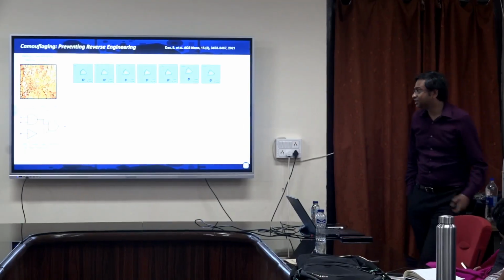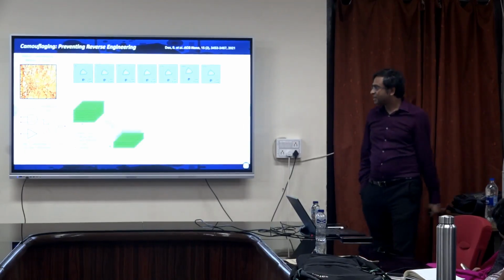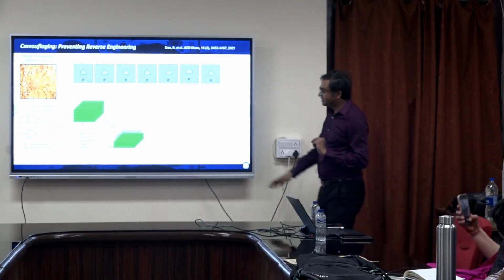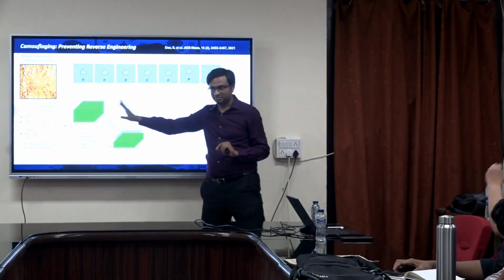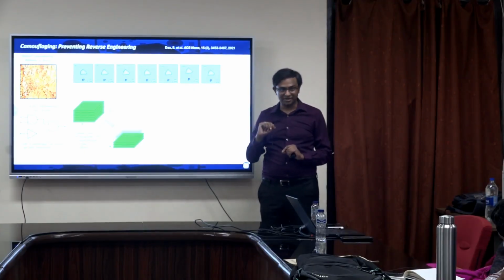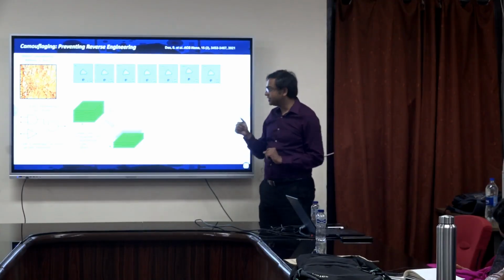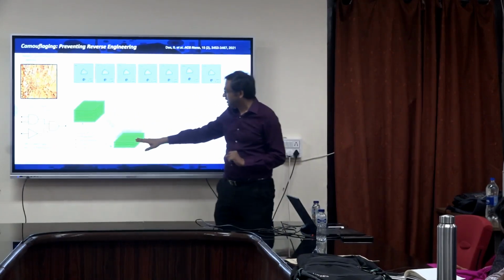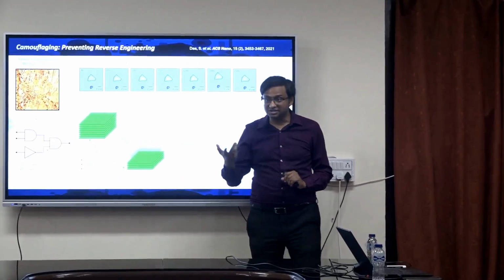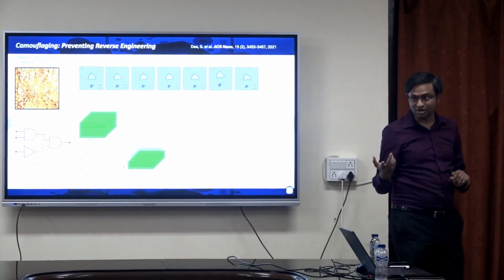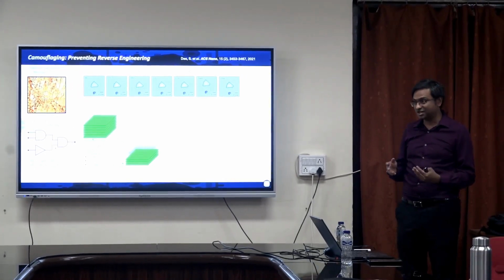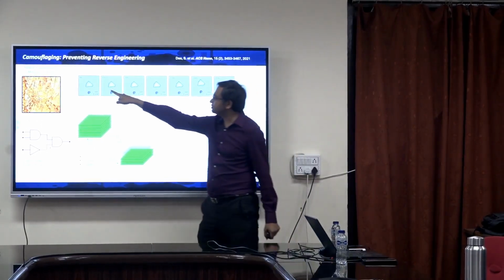That is possible with the 2D material because of this. If you have not a monolayer flake but a multi-layer flake, then this material is primarily N-type. Most of the 2D materials are N-type. Then we spoke about this oxygen plasma treatment, didn't we? When you treat it with oxygen plasma, it's a self-limiting process, but you can convert the top layer into a transition metal oxide, like molybdenum oxide or tungsten oxide. And these oxides are transparent, because most of the oxides are transparent. So the appearance of the flake does not change.